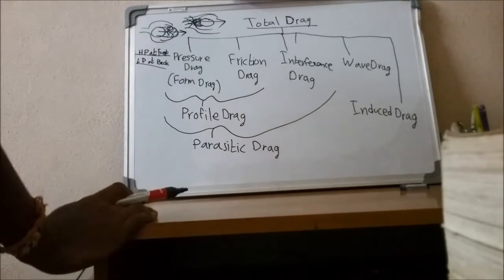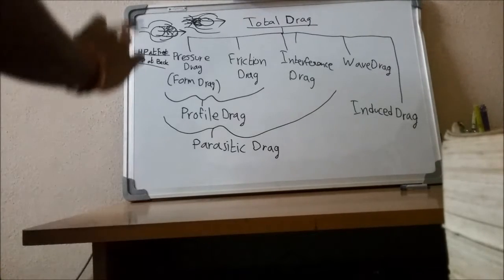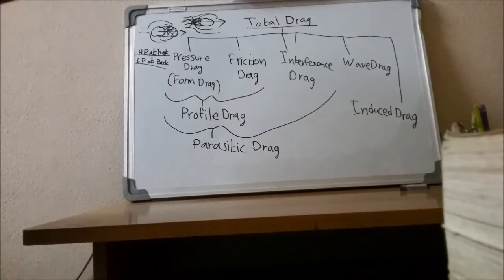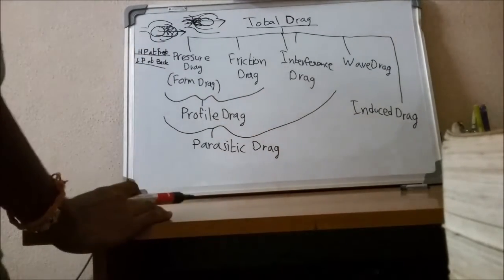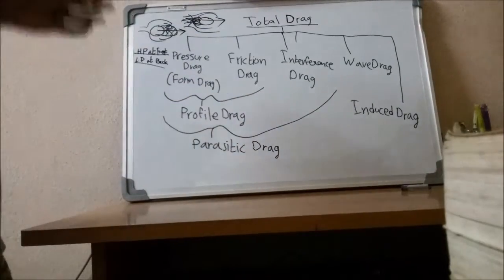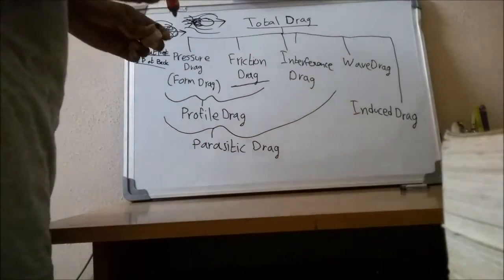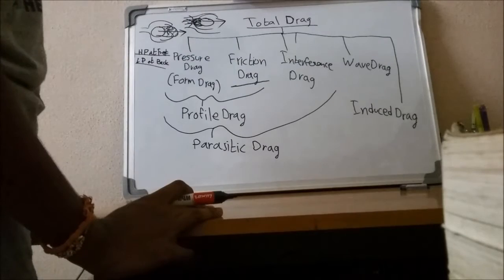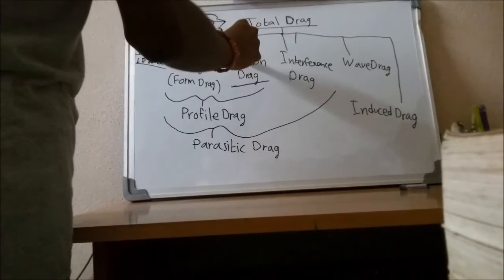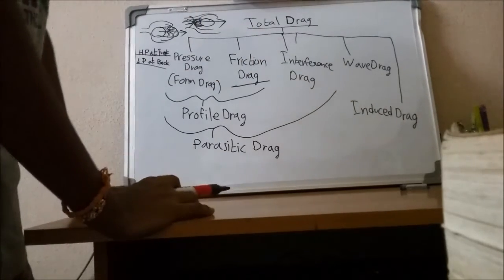We can generally observe it at some top portions of automobile cars, on the hood portion as well as the rear windshield portion. So this is the general idea. And friction drag is caused due to the fluid and body interaction, and this is where boundary layer theory comes into the picture. Friction drag is directly proportional to the thickness of the boundary layer.